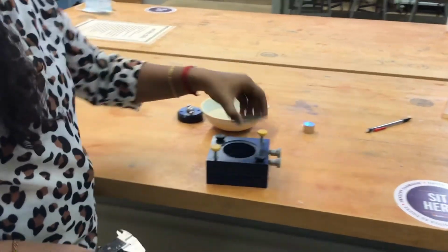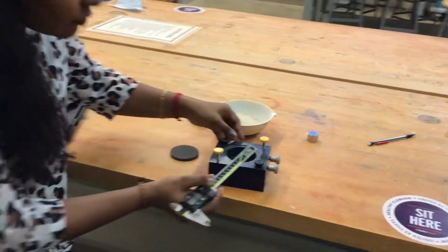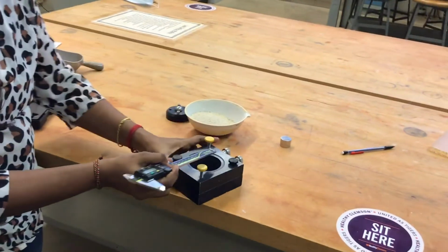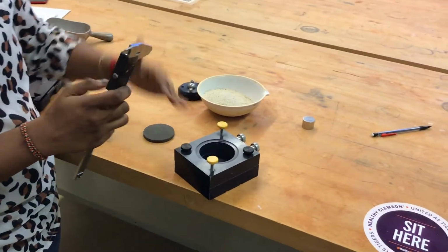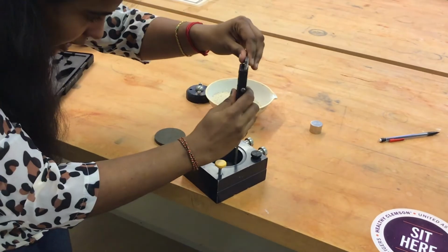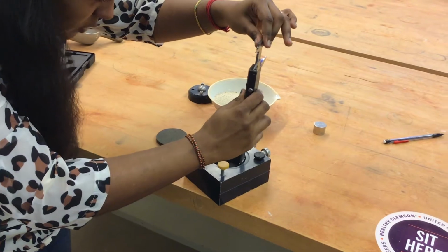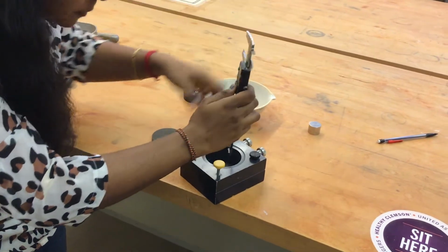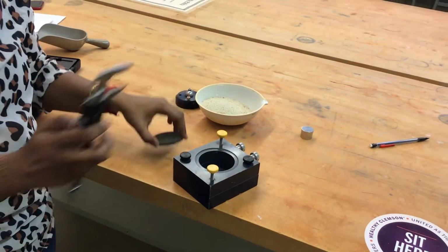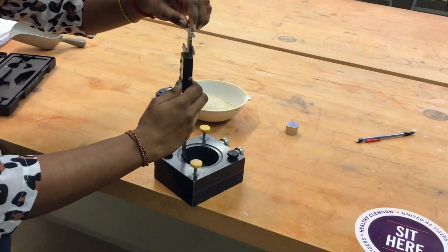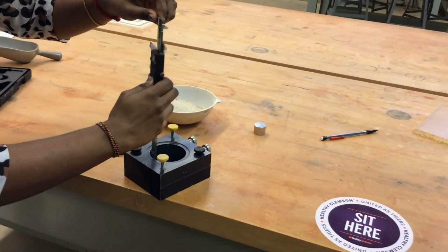There will be a porous stone on the top, and there will be a line marked over here in a black line. So you need to leave space for the porous plate and then get the height very carefully. It is better to take more readings to reduce the error, because the porous plate surfaces will not be very horizontal. So I recommend taking more readings so that you can get the average, and it will be more accurate.